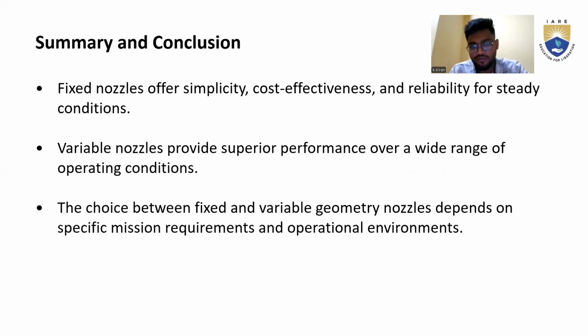Based on the operational environment, we can say there are considerations of cost effectiveness and reliability also. In a fixed nozzle, there is cost effectiveness and reliability for steady conditions, and they simply offer that. At the same time, in a variable nozzle, it is mainly performance over a range of operating conditions, meaning based on the situations and applications they can follow that principle. At the last point, both depend on the specific missions and requirements of the environment.